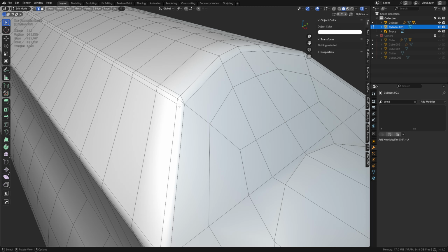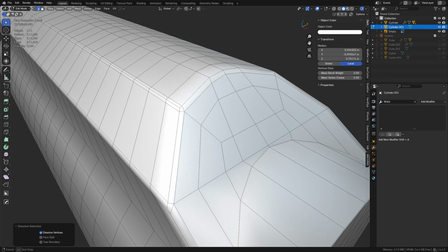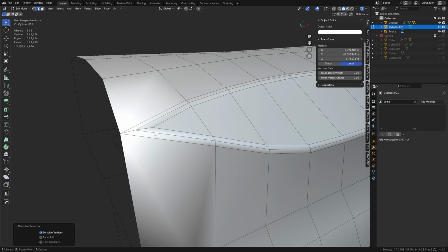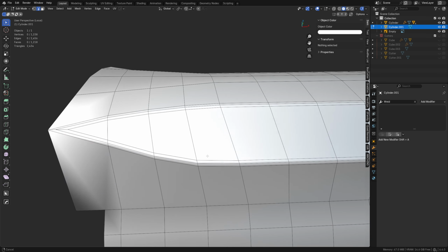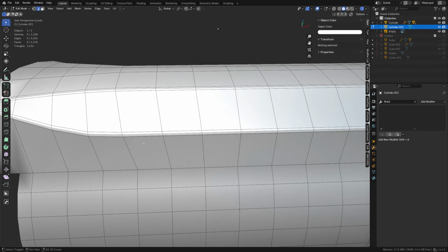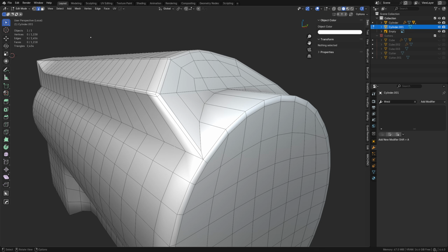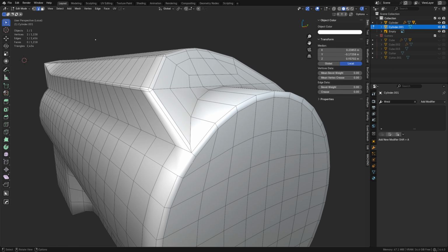This one we can probably just cancel out right here on that edge. No problem. And the back side of this, I already knew it was going to do this. So this is kind of what's going on here. And that'll work there for that. As for the other ones, if we wanted to do more holding edges, we could do chamfers. We don't always have to use 2 segment bevels, right? There's nothing wrong with doing a chamfer, but in our case here, I don't think I would even bother putting an edge down here, okay?